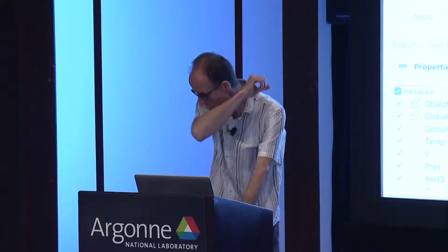Before this file is loaded, notice we can set that we want to load only certain variables. In our case, we want to load them all. This is useful to save memory if you have very large data sets. Yeah? It's not the case here, so we load everything. It's just a disk with a hole in it. It's a cylinder with a hole in it. And it has several data values here. For instance, you can color by pressure.